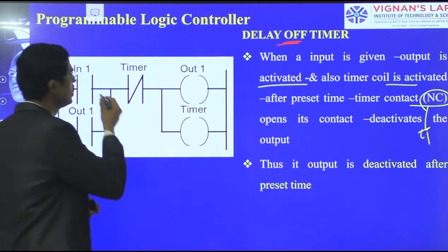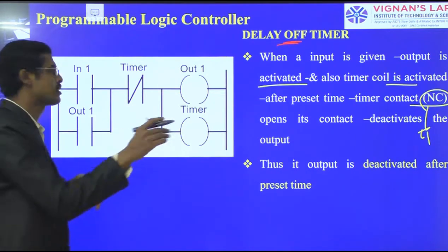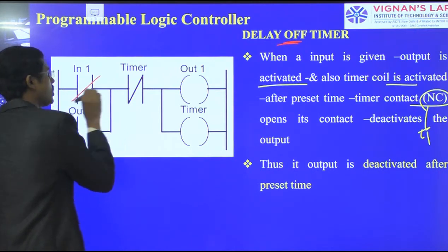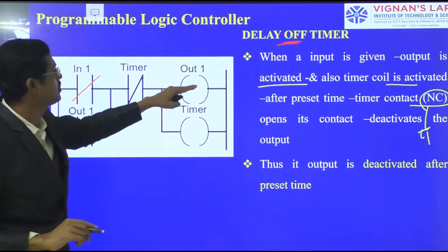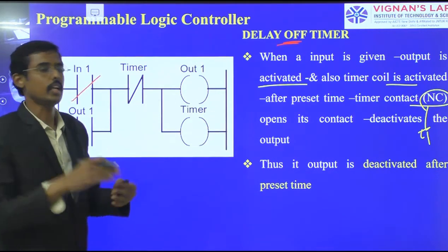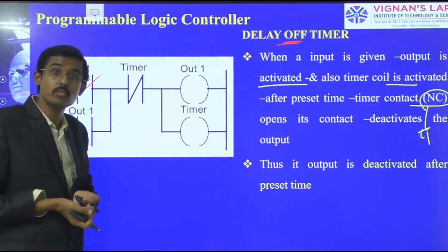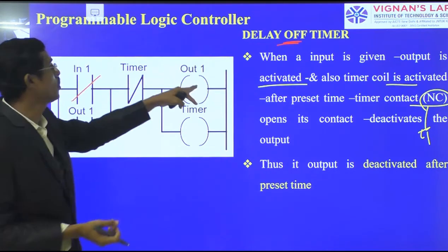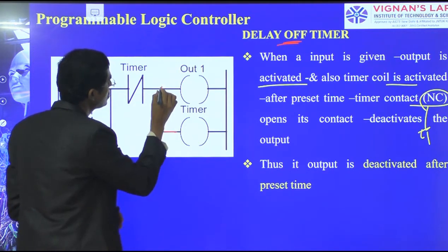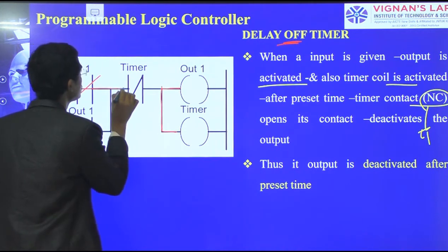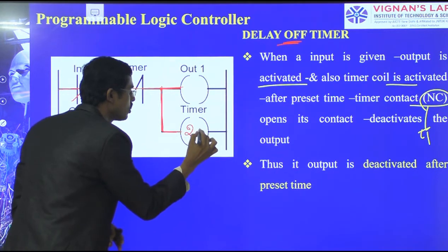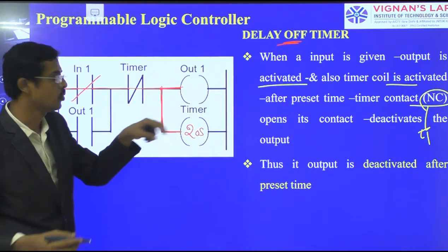You see? Now I have given a start, and the trolley has moved. I have started this and it has started to move. And the output has been started. Output means the operation of the moving motor has started and the trolley is moving now. How long should it move? At the same time of switching on, the motor should start and move. At the same time, I am going to count. This is activated. This line is moving. When the contact is closed, the current goes to the motor and also to the timer. So I am giving 20 seconds of time. So now 20 seconds is counted.